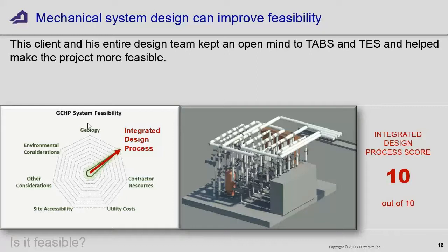But what I'm interested in is that I know for sure it's going to reduce the size of the ground loop. Heating and cooling loads are going to be smaller, and that's going to reduce the size of the ground loop. That's the whole point of the exercise. If you've got a design team that's willing to work with you on this kind of stuff, and they're not always, but if you can show them on an energy model that if you change the glass from this to this, this is what happens to the size and the cost of the ground loop.